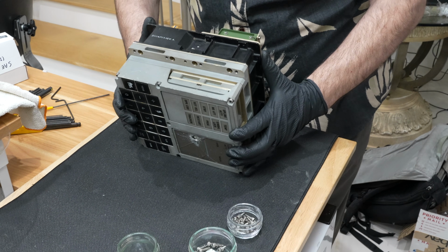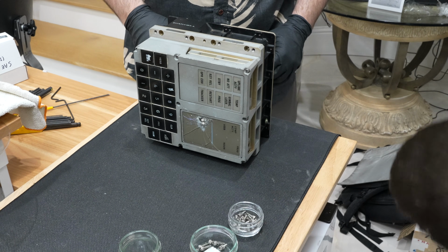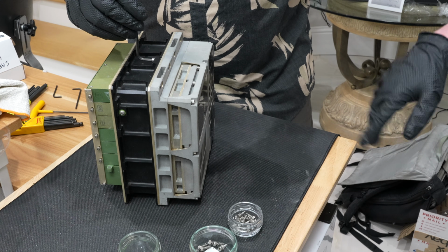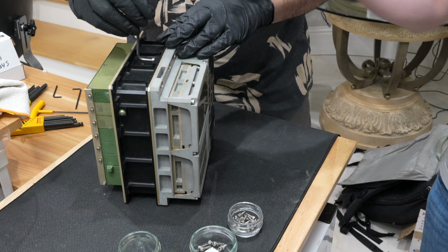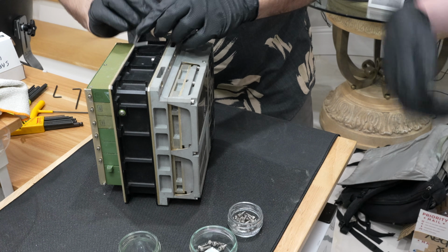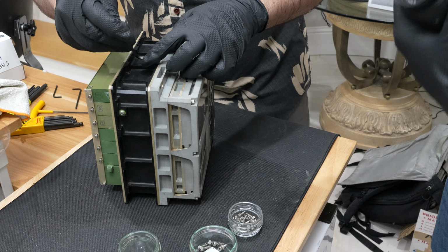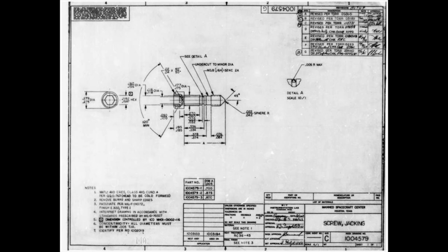Alright, and that's all the screws holding the 2 layers together. Take a look around. So we're tightening these to push it? No, loosening. There's an E-clip there that is holding the screw captive. Oh. But you only want to go a little bit and then start turning the other one to back it out evenly. Aha, we have just encountered a jacking screw.